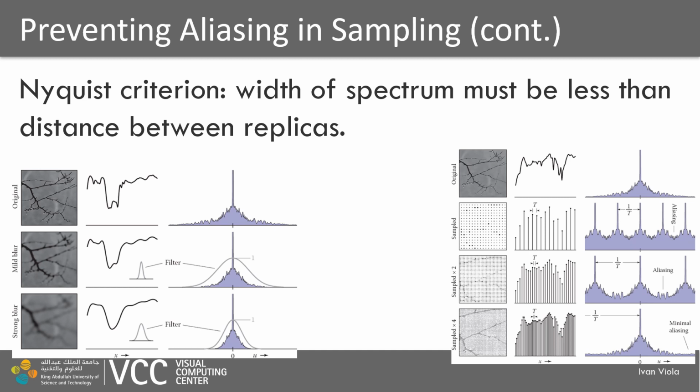Band limiting would mean that we are pre-filtering our signal so that we are setting some frequencies to be equal to zero. And by that, it means that we are disregarding certain high frequencies. Our image will get more low pass filtered or blurry, if you like, but we will be able to represent it with our filtering scheme.